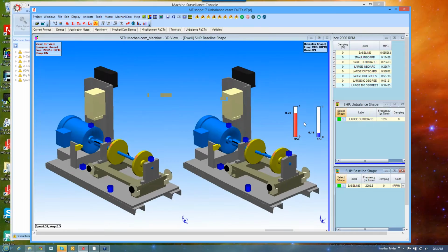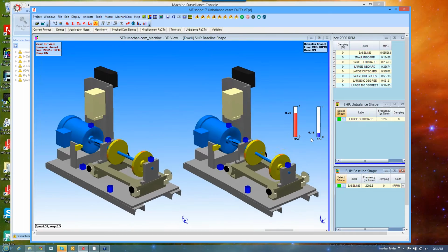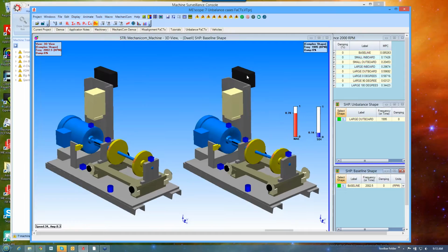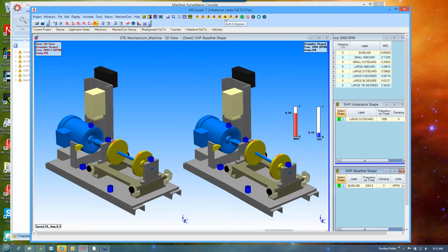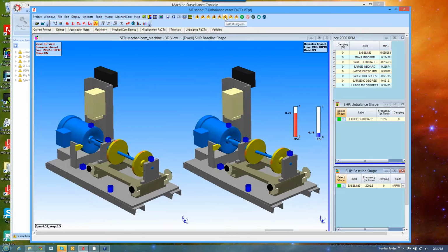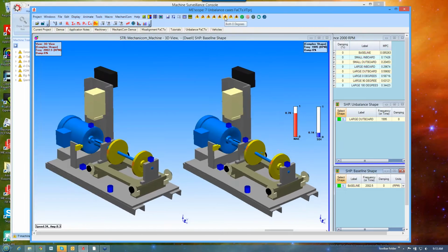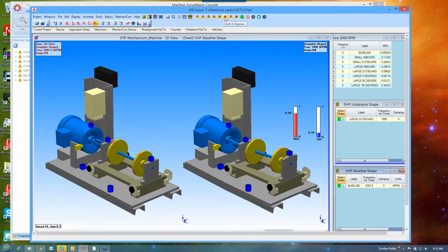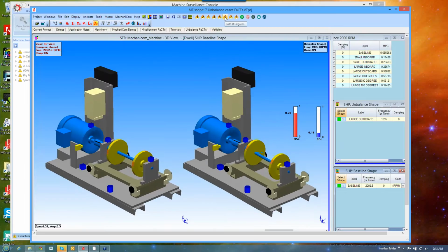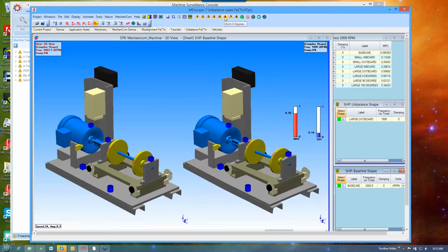Again, MAC value didn't change a whole lot, but the SDI is dropping because it's a more severe case. All right, here's the worst case, both at 0 degrees. This is where we got 2 weights, one on each of the inboard and outboard, but at 0 degrees, so that as the machine runs, those 2 weights are causing the largest unbalanced forces of all the cases.